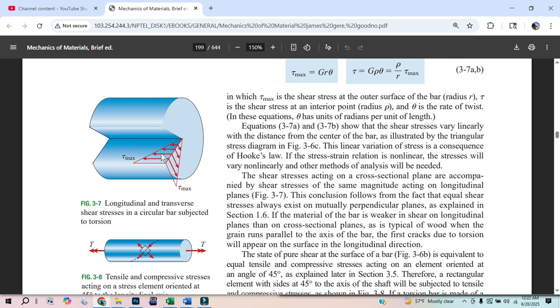But if I add that disc next to another disc, next to another disc, and this is a 1 meter long steel shaft, then that angle is still 0.004. But 0.004 times the radius, radians times radius, is 4 millimeters, which is the circumference distance that will get rotated. And I think for that first proof, it's way better if you think of how much this is rotating in circumference, because that value doesn't change.